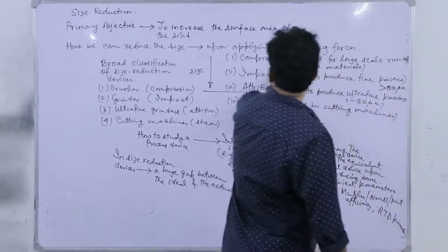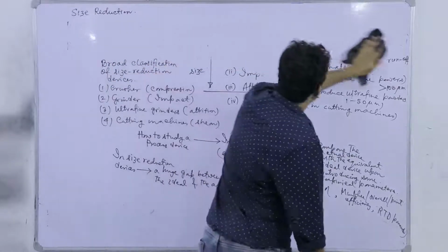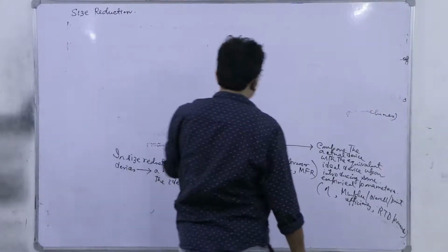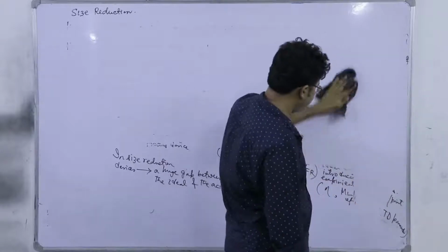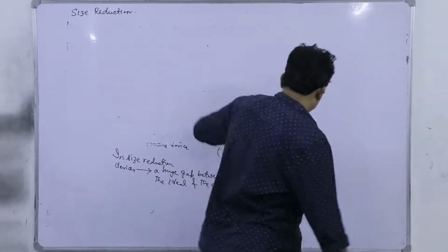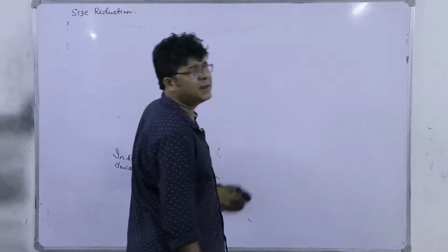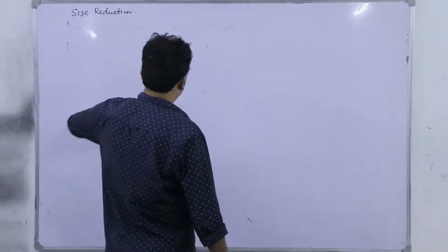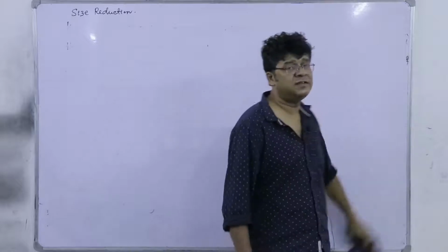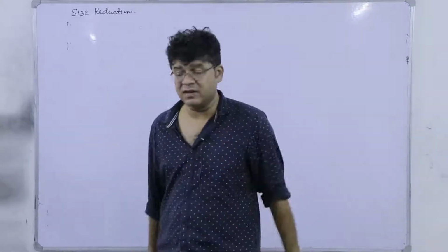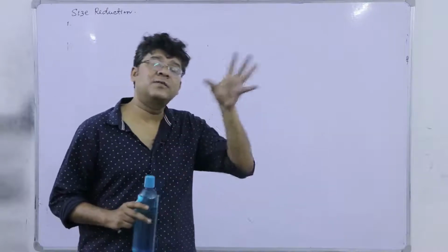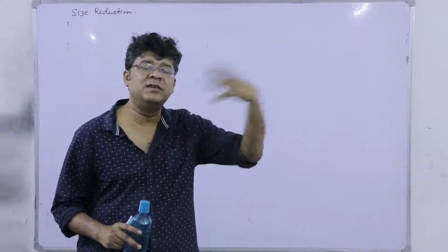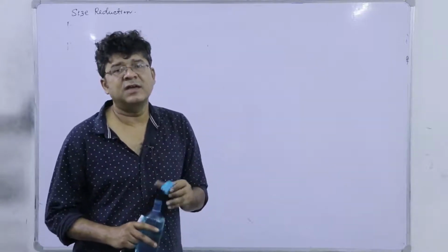See, the standard equation we derive from the basic physics of that system is not going to work, as we have to include the empirical parameter of efficiency, which has a very, very small value like 0.6 to 1%. That means 0.006 to 0.01. So that's the range of efficiency for a crusher. You can understand that whatever we calculate theoretically, if that factor changes a little bit, there will be a huge error in our calculation.